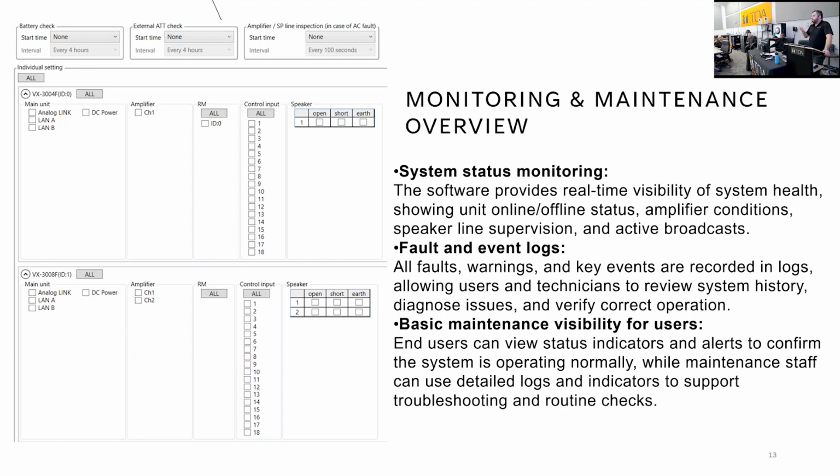Of course they can adjust the volume for background music because it's too loud, but during emergencies we can override that. Some attenuators have an override contact. We can show a little bit in the software how to enable that, but in emergencies you override. But to tell if somebody reduced the volume, no, you cannot do that.